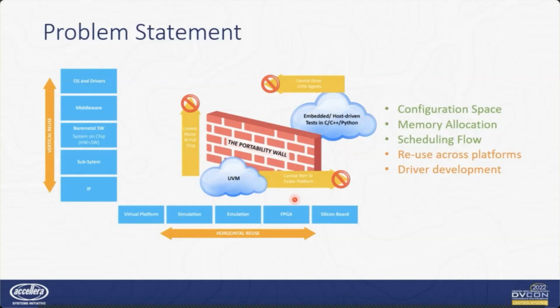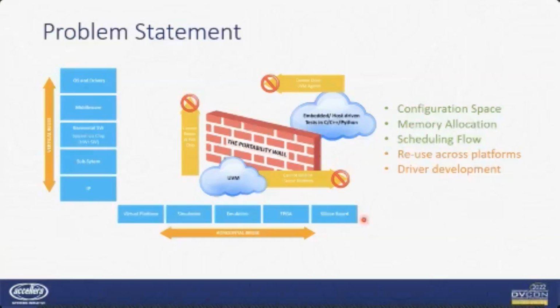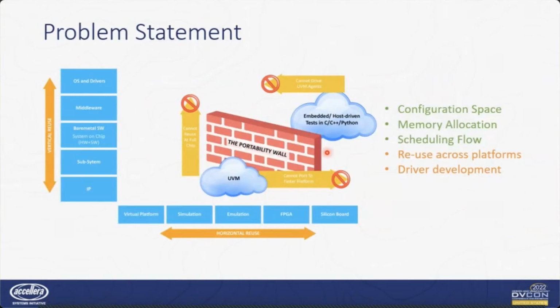The second approach is pretty much similar, where you have one single C function call in your exec body. That is a single exec body for both your UVM and your embedded tests. But the C exec body basically calls a C function, and the C function would either call a UVM task via DPI calls or a C driver function. And here both the UVM task and the C driver have the same name and parameter definitions. So with either of these methods, you would still require to develop both your underlying UVM sequences and your C driver code. So this is basically a duplication of effort, and this is where HSI comes in to save the day with a single implementation of your driver code.